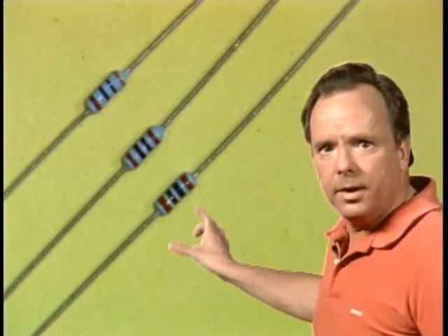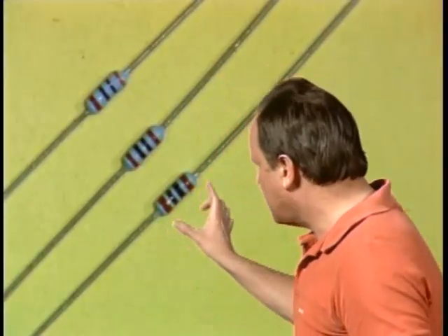Resistors are generally classed as fixed or adjustable or variable depending on their construction and use. A typical fixed resistor, like this one, consists of a small rod of carbon compound. So here's a typical fixed resistor. Now, an adjustable resistor is usually a small wire-wound type with a metal collar that can be moved along the resistance wire and it lets you vary the value of resistance placed in the circuit. And a variable resistor is arranged so that it can be changed in value any time by the operator, generally with a knob. Variable resistors are commonly known as rheostats or potentiometers.